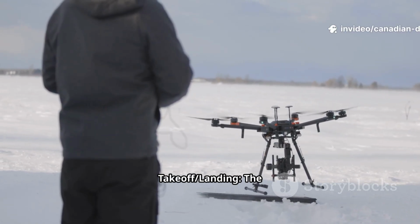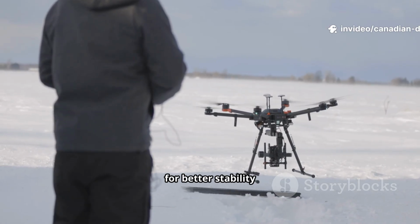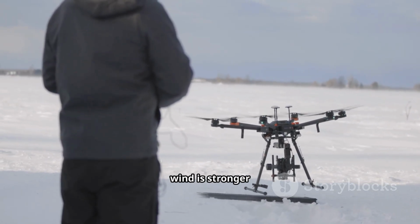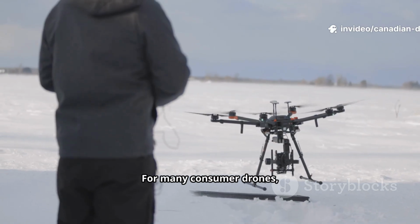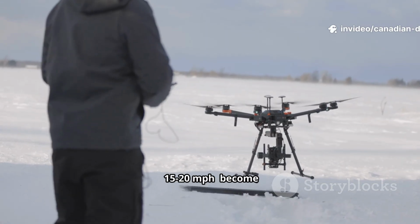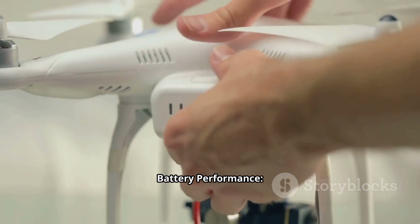Takeoff and landing. The most critical phases of flight. Always take off and land into the wind for better stability and control. Rule of thumb, if the wind is stronger than about 2/3 of your drone's maximum advertised wind speed, do not fly. For many consumer drones, sustained winds above 25 to 30 kilometers per hour, 15 to 20 miles per hour, become very risky.